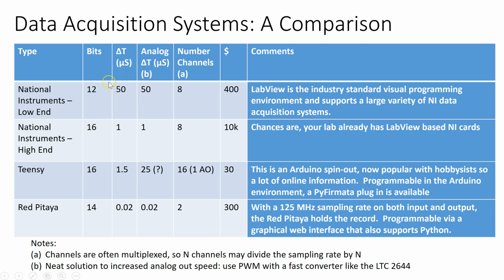The time interval of sampling is 100 microseconds, which is a long time. 100 microseconds is 1/10 of a millisecond, or 10 kilohertz. So these things are down around the 10 kilohertz range. Remember, the Nyquist theorem brings you in a factor of 2. There is an analog output which puts out on a similar time scale, so once again about 10 kilohertz.